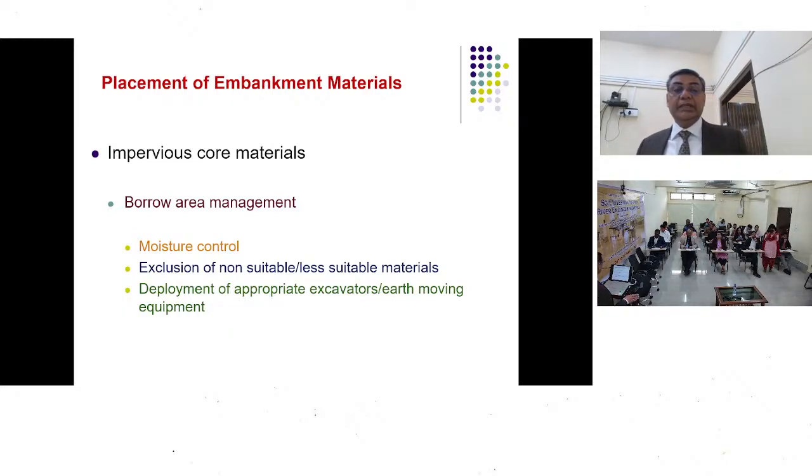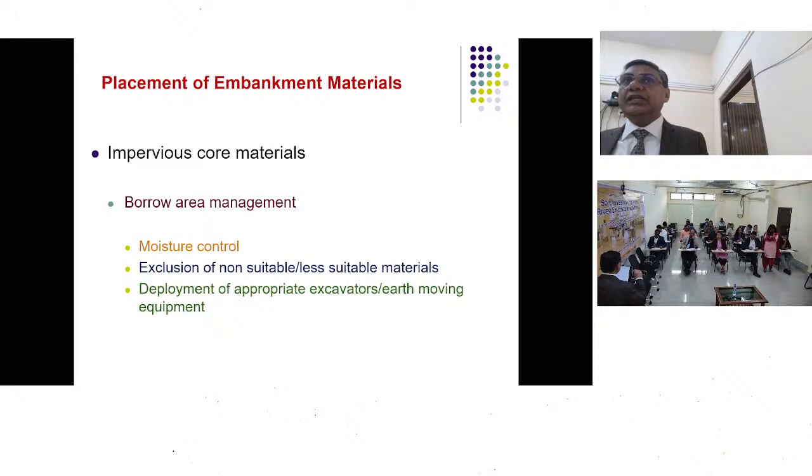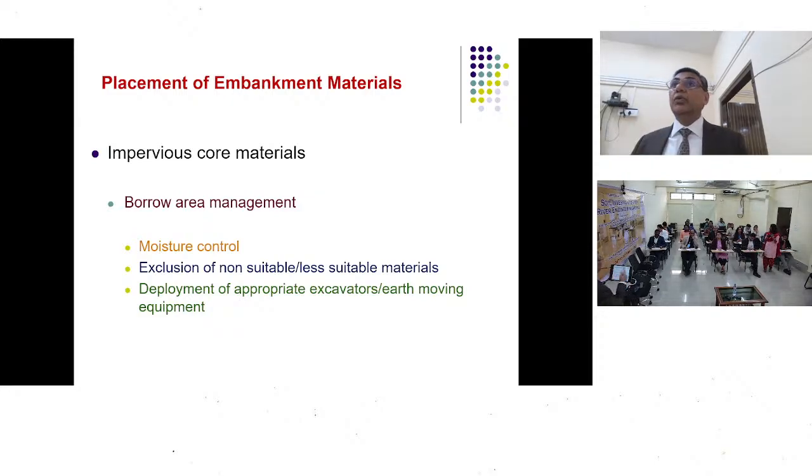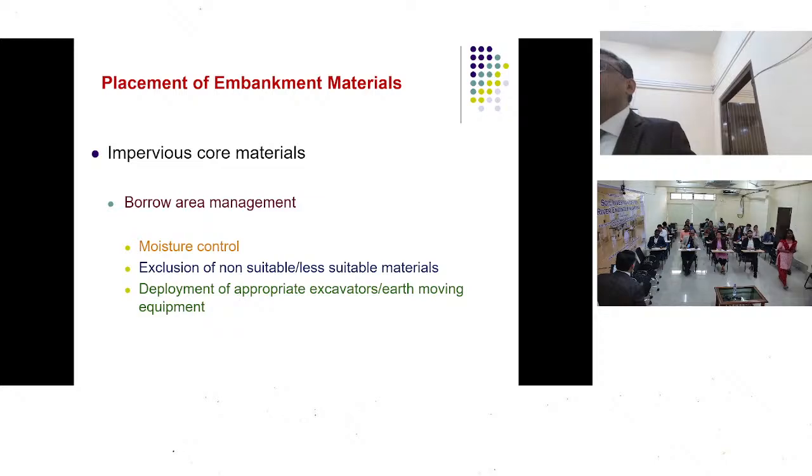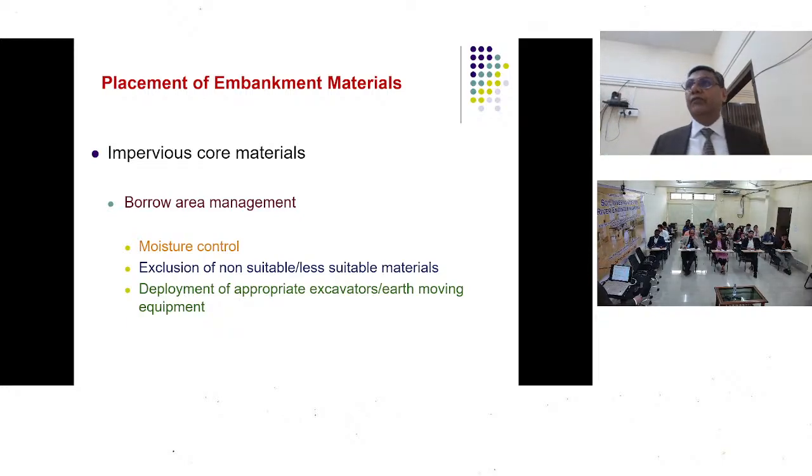Again, for impervious material, we need to go in for borrow area management, moisture control, exclusion of non-suitable or less suitable materials, deployment of appropriate excavators or earth moving equipments. Moisture control, you are going to check the moisture at the borrow area. Again, as I was saying, you calculate what is the additional moisture which is to be put in, or in case the moisture is more. How can the moisture be more in the borrow area than the OMC? Can it be more? It can be in case there has been a rainfall.